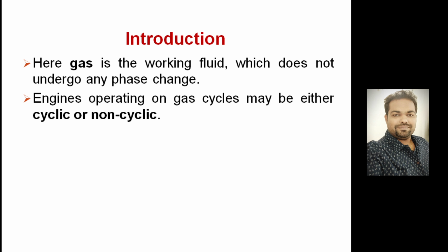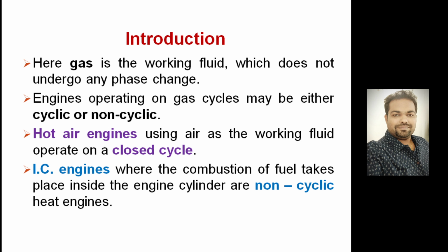So, what are gas power cycles? Gas is the working fluid here, which does not undergo any phase change. Engines operating on a gas power cycle may be either cyclic or non-cyclic. The hot air engine uses hot air as the working fluid and operates on a closed cycle. IC engines, where the combustion of fuel takes place inside the engine cylinder, are basically non-cyclic heat engines. An IC engine has different kinds of strokes and all the processes are different, so they are known as non-cyclic.